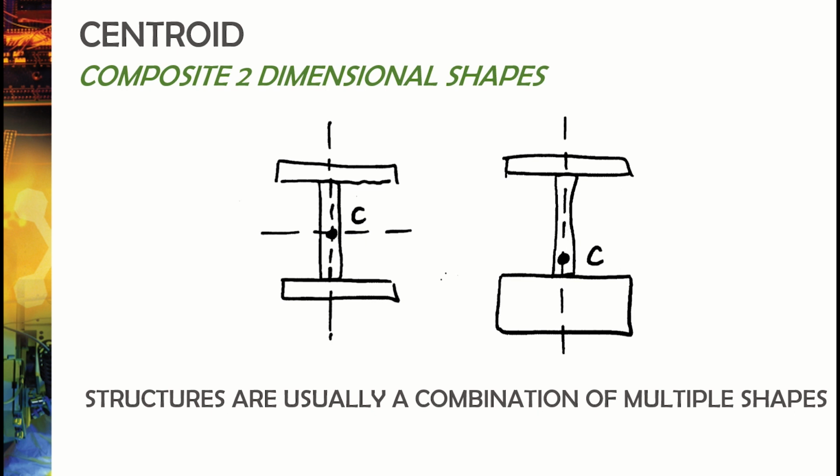Both have the same shape, however, the one on the right has a much larger base. As a result, you can see that the center of mass of that shape is shifted more closely to the bottom, or where their mass is at. As we've discussed before, the center of mass of a shape is going to have a lot of impact in terms of the structural integrity of a system, especially in a failure method called buckling, which would be the bending of this particular member.